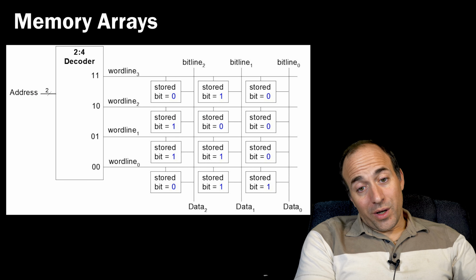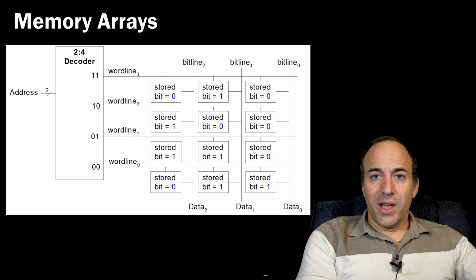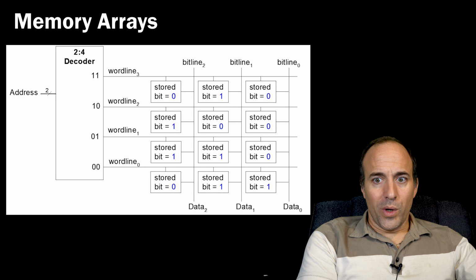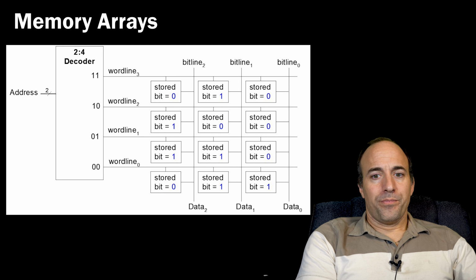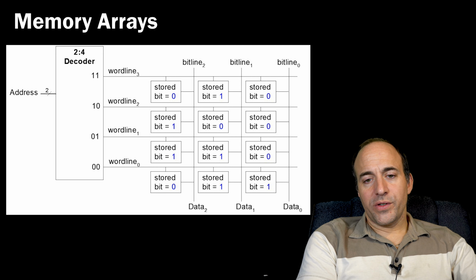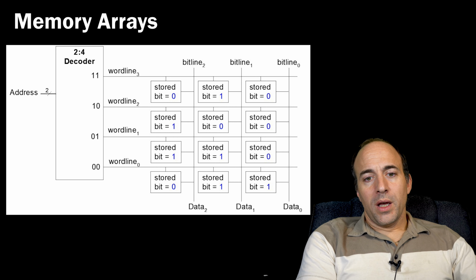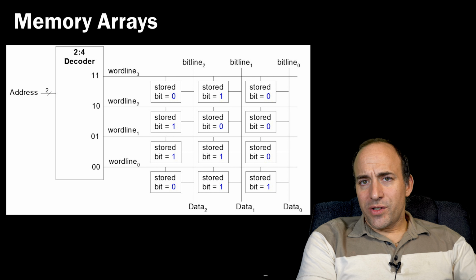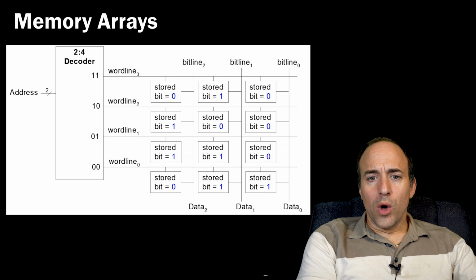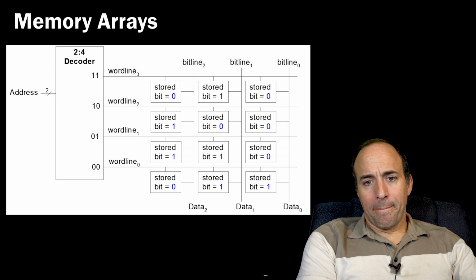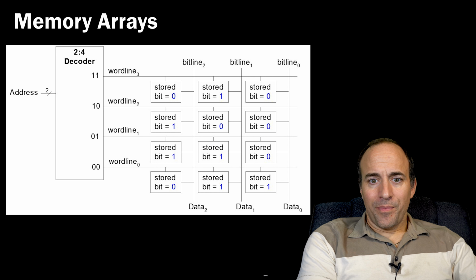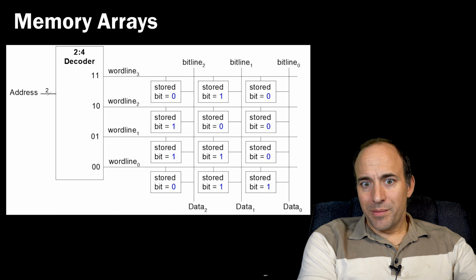All RAMs, though, including flash, are generally arranged physically as a two-dimensional array of cells where each cell contains one bit. We'll assume for this discussion that the RAM has one memory port. So inside of this two-dimensional array of cells, there is one word line for every row of cells, and there are a set of bit lines that connect each cell in each of the columns.